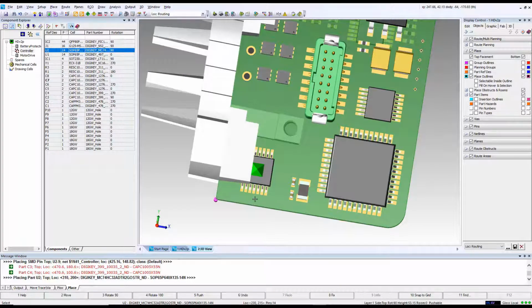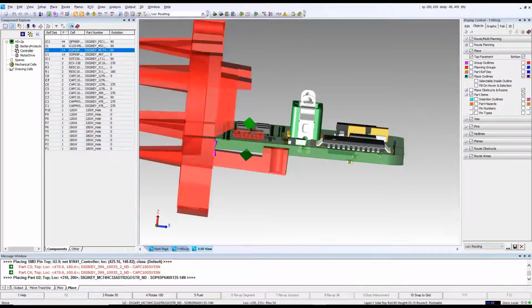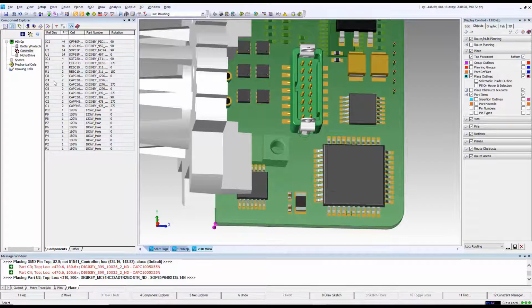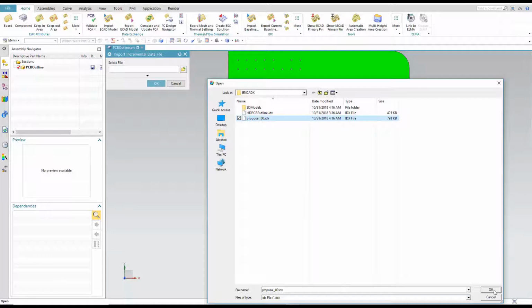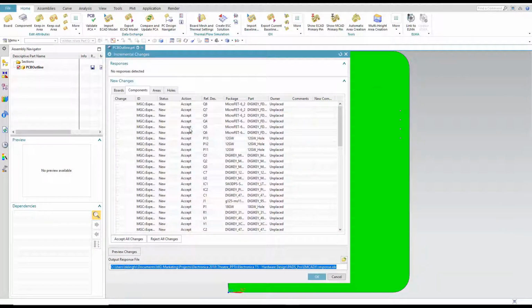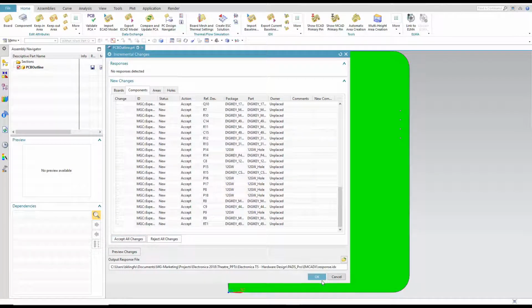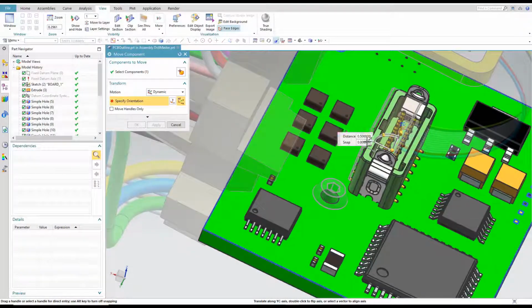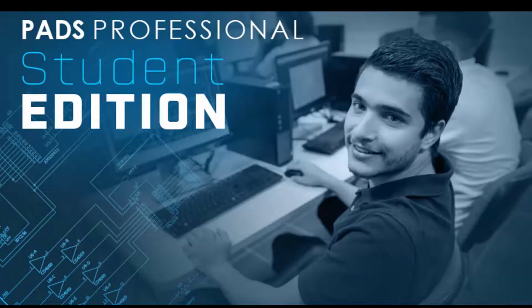Placing components in this 3D view allows clear visuals of any physical hazards, which might not be as apparent if you're using the layout in 2D mode. Once component placement is complete on the ECAD side, you're able to import this information to NX. Not only can you directly import to MCAD, you can accept or reject changes. Reviewing board, component, area, and hole changes allows both ECAD and MCAD tools to stay synchronized and in strong communication with one another. Changes made in NX will be sent back to PADS Professional in the same way, with the ability to accept or reject.